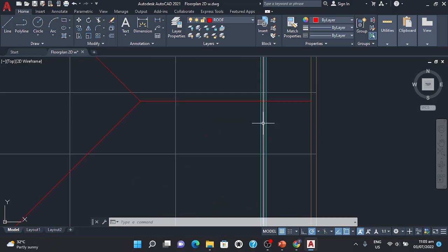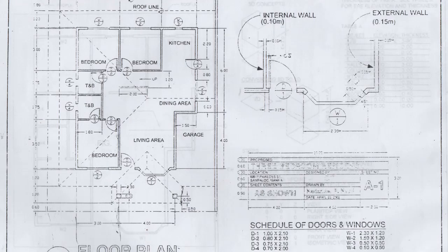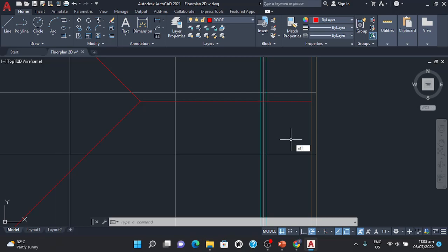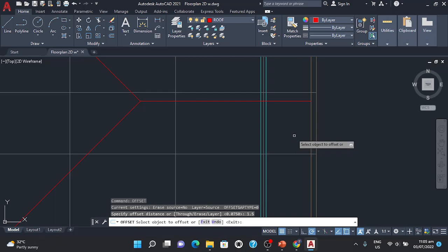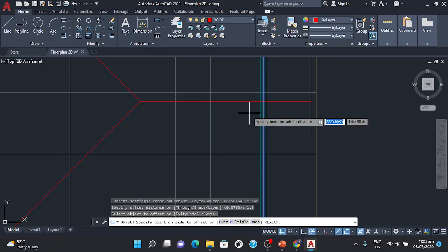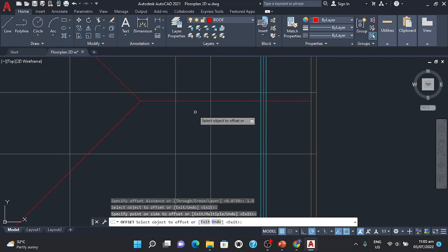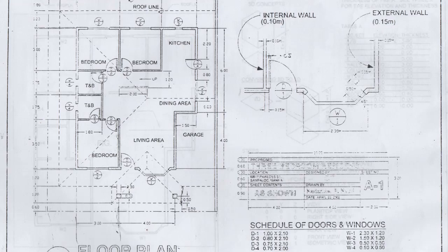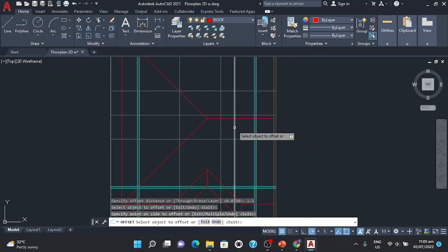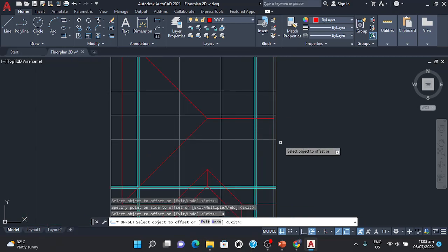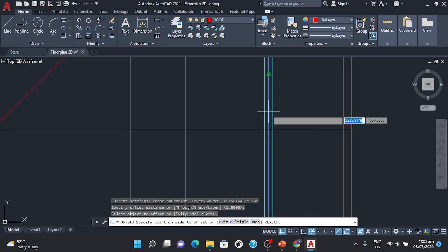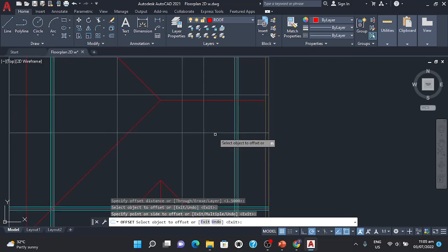So for this one, click this. Okay, click this line and create an offset of 1.5. So offset, specific distance. So we have here 1.5 based on our handout. Select this specific object and drag this to the left and hit enter. Okay. The next one, we have here offset distance of 4. So for this one, let's undo first, offset. Again, let's redo. Offset 1.5, drag this to this one. Okay.